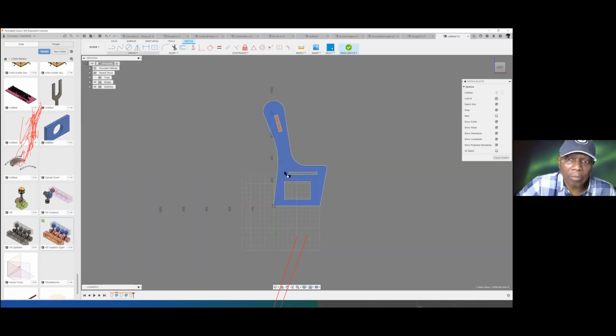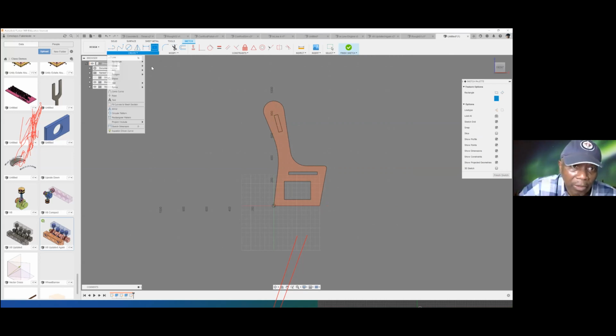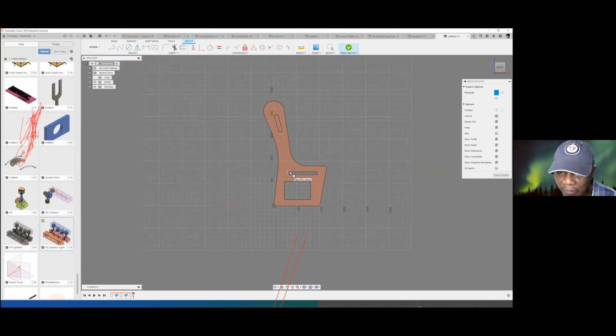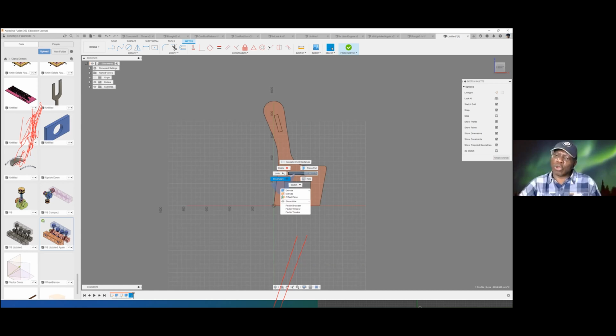So I can create something here. I want not a center rectangle this time. I want a rectangle. I want a rectangle that is 2 point. So I can choose a 2-point rectangle. Okay. So I can press pull, which is a way to call the extrusion.